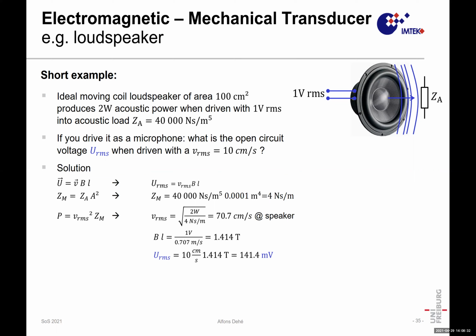And the question is, if we use this as a sensor, so we have a sound field with an RMS velocity of 10 centimeters per second. Typically, if I speak to such a speaker and I put a voltage read on the other side, can this work as a microphone? Yes, it can. Simply, you use the formulas of acoustical and mechanical impedance that are given here, and the force out of electromagnetic transduction of this system.